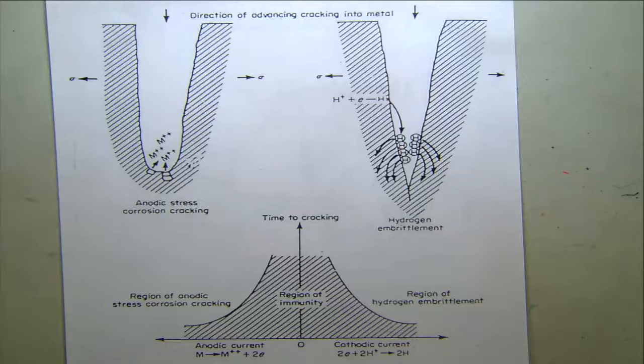Yes, absolutely. Regarding this embrittlement and this one, corrosion rate, do they have some difference in, like, maybe color? No? Can we identify it? Well, I'm going to tell you about the hydrogen embrittlement in a minute. Yes, quite often there are a number of features that make it different. One is that you're likely to get corrosion products, so you've got oxides and magnetite perhaps, or a passive film. The other thing is, as in the drawing, the cracks are just that little bit wider. These tend to be sharper and narrower.